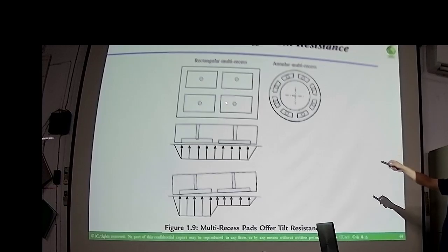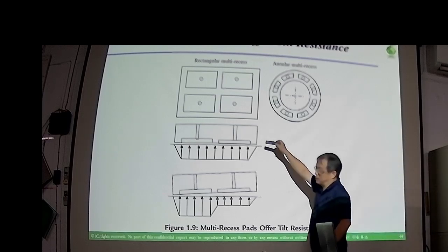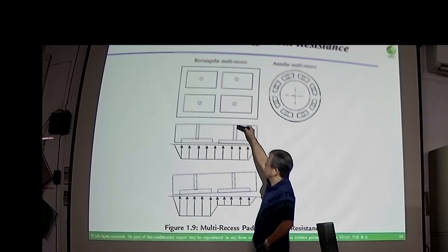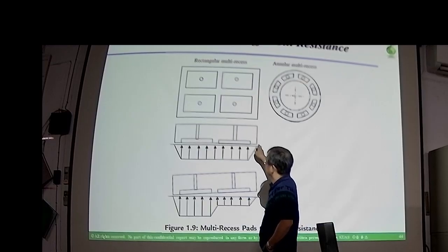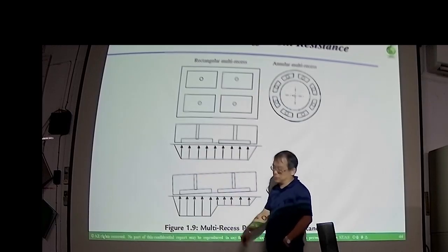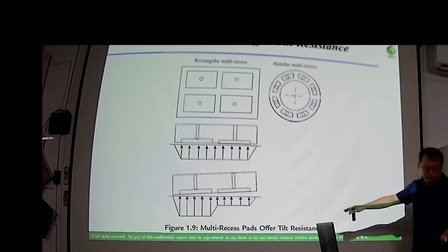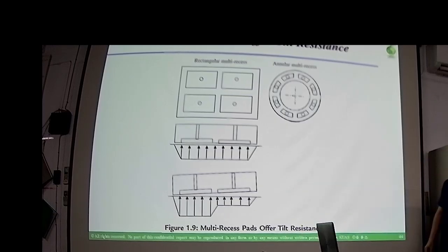So the oil is pumped into the bearing recess, so you build up the pressure distribution. With the pressure distribution here, you can sustain the external loading.